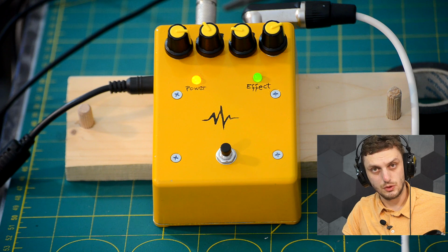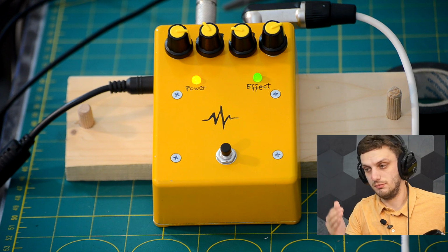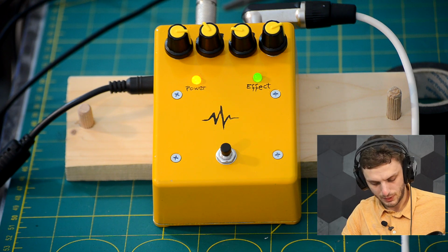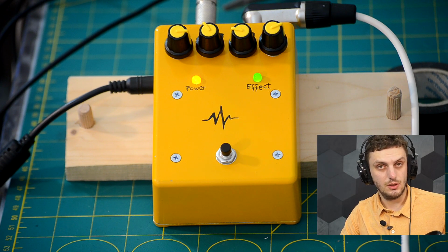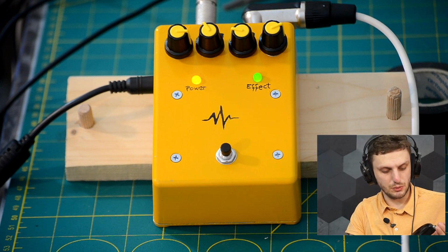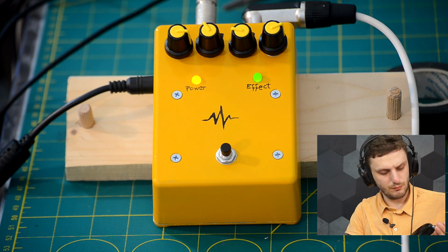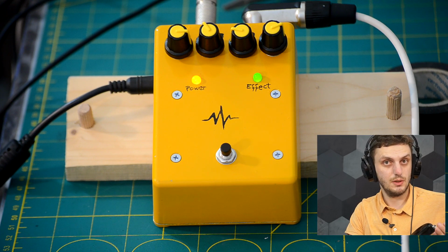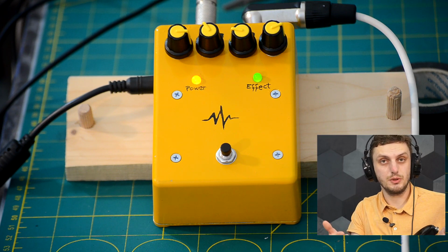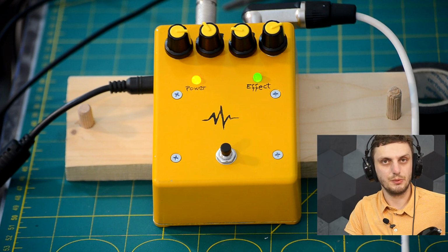One of the interesting effects that this circuit produces is that if you play two strings, one that is not struck very hard, so you can just barely hear it, but then you play another string and you strike this one much harder, the volume on the first string will abruptly decrease. That's because the maximum volume can only have a certain limit, so the circuit is amplifying whatever signal it's getting to this limit.